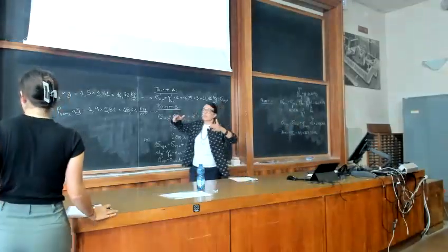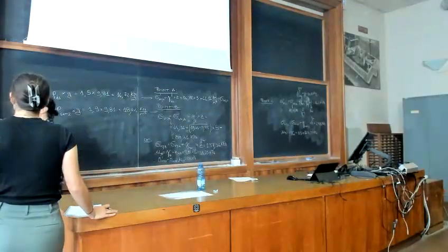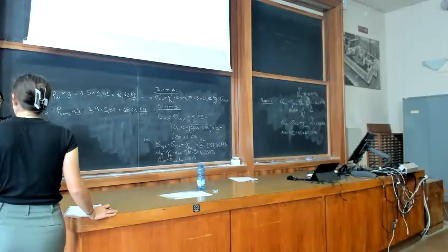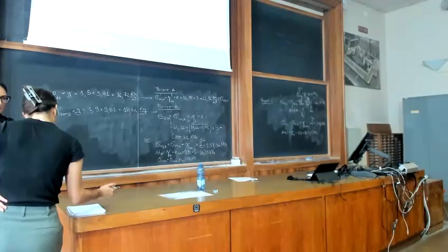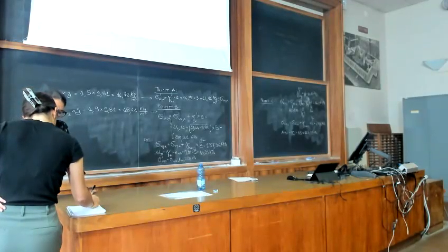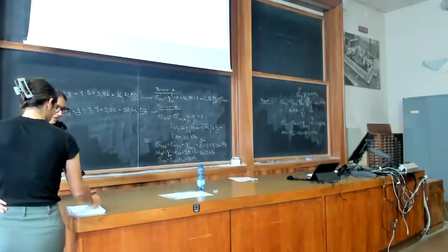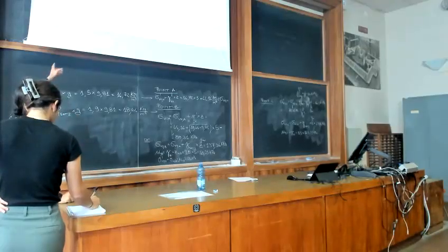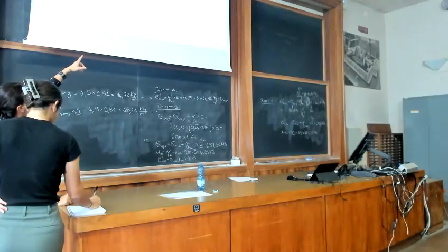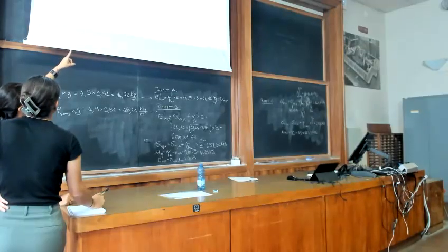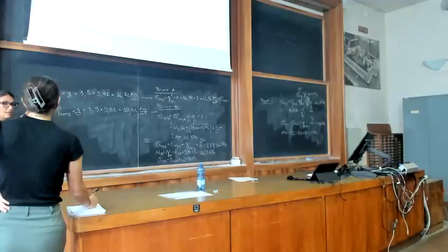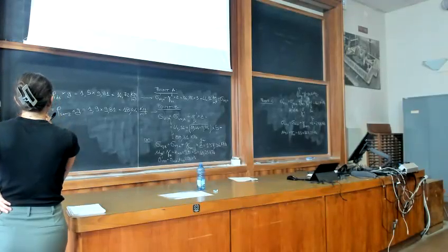So above the groundwater table the soil is dry. We have no water there, so pore pressures are zero. Then we have a linear increase of water pressure when we are below the groundwater table. We need the unit weights of soils in order to calculate the initial stress, which is from the density, from which you get gamma. Usually I provide gamma.